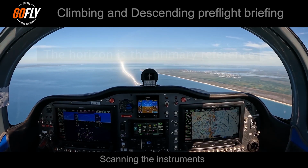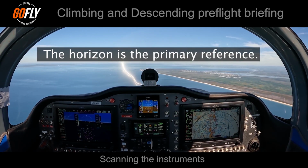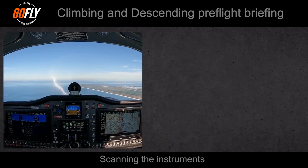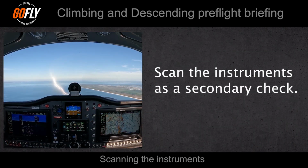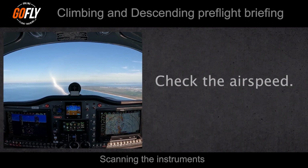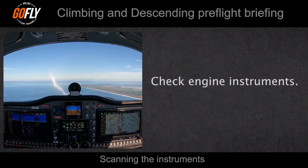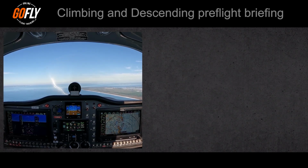However, we must remember as visual pilots, your eyes should still be on the horizon for the majority of the time. We scan the instruments quickly as a secondary check to make sure we are climbing and descending at the correct airspeed, we have not flown through our nominated attitude, and that our engine RPM, temperatures and pressures are all within safe tolerances.